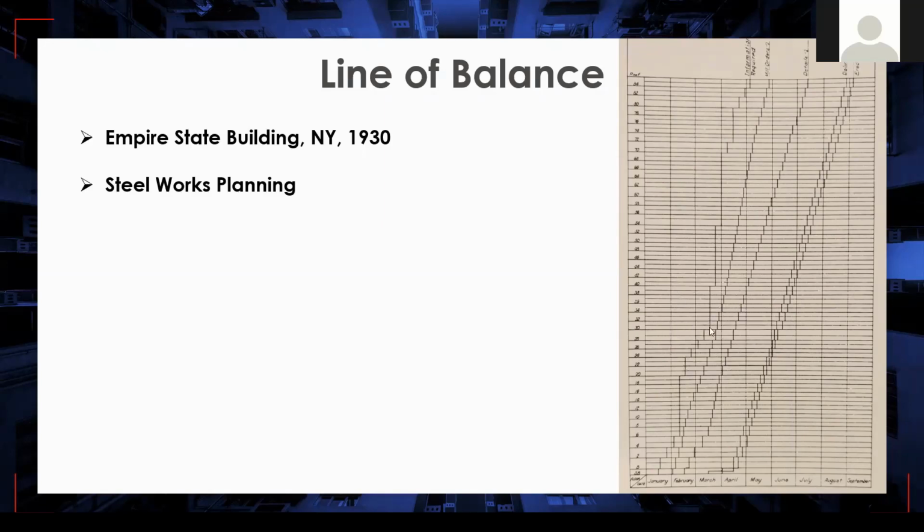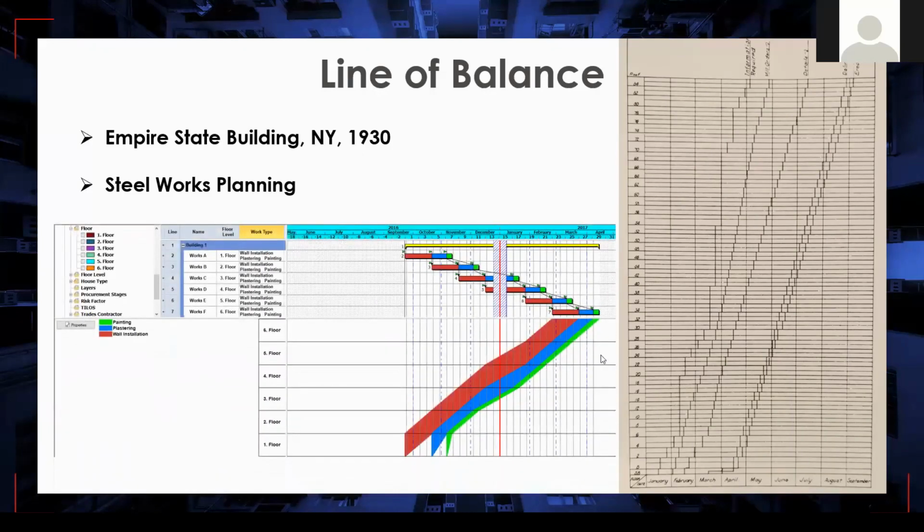So we need to make sure that these are not clashing on the same location and in the same time frame. We can give an instance: for any wall installation, we have an activity, and after that the paint and the plaster follow. Within the sample, we have a paint, plaster, and the wall installation. So after the plaster activity finishes, the paint cannot start. So if we have any other situation on our views, we'll be making sure that we correct these activity relationships.